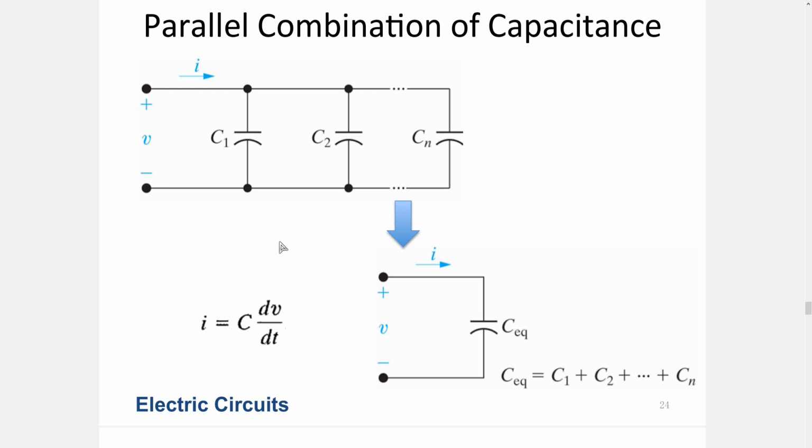So in order to increase the capacitance, you need parallel combinations of capacitances. This is again opposite when you compare it to the case of the resistors or inductors. However, this is how the equivalent capacitances are found. You simply add them. If you have parallel connections, it's very easy to compute the equivalent capacitance. If you have a series connection, then you have to deal with the reciprocals, which might be a bit cumbersome, but computable, given the fact that we have scientific calculators. So it can be done.